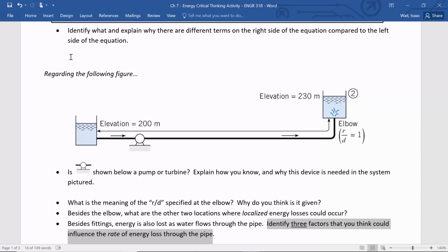You don't want to give them too much pressure, because it just costs you money to make the pipes big. So you're going to give them just enough pressure so that people don't complain, the minimum amount of pressure. It's kind of like the currency you've got to spend: the energy being delivered at every point in the system.